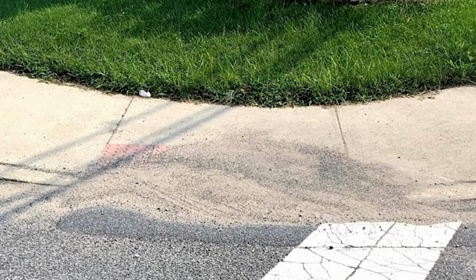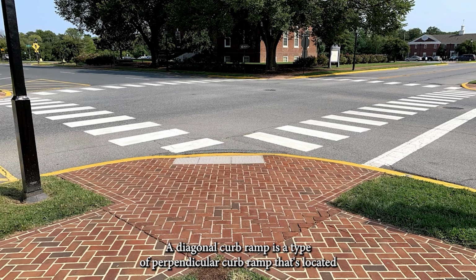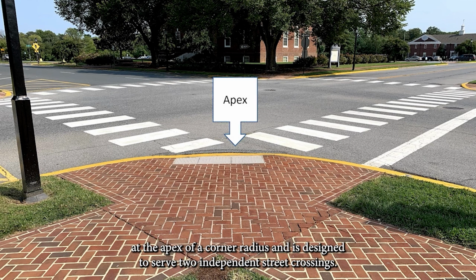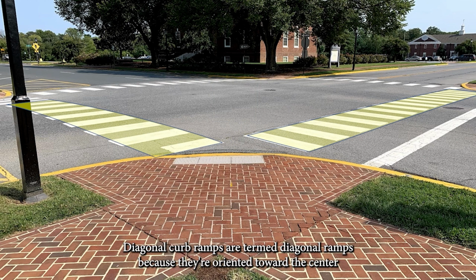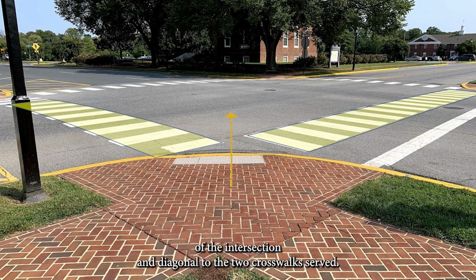A diagonal curb ramp is a type of perpendicular curb ramp that's located at the apex of a corner radius and is designed to serve two independent street crossings. Diagonal curb ramps are termed diagonal ramps because they're oriented toward the center of the intersection and diagonal to the two crosswalks served.